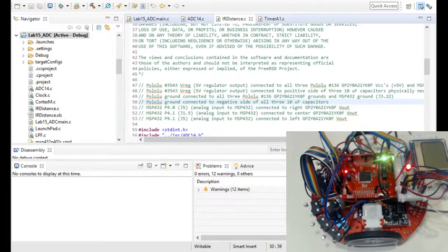And one thing that was suggested, because these Sharp IR sensors are so noisy, is to add capacitors. So I have 3 capacitors up here. So I have the wires coming up, going to the capacitors, and I have power going to that. So those are capacitors between ground and power for each one of the IR sensors. And so that's adding some more stuff to that. So yeah, it's got a ton of stuff that's going on here. Oh, and there's wires for the encoders of the motors too, but that'll come later.